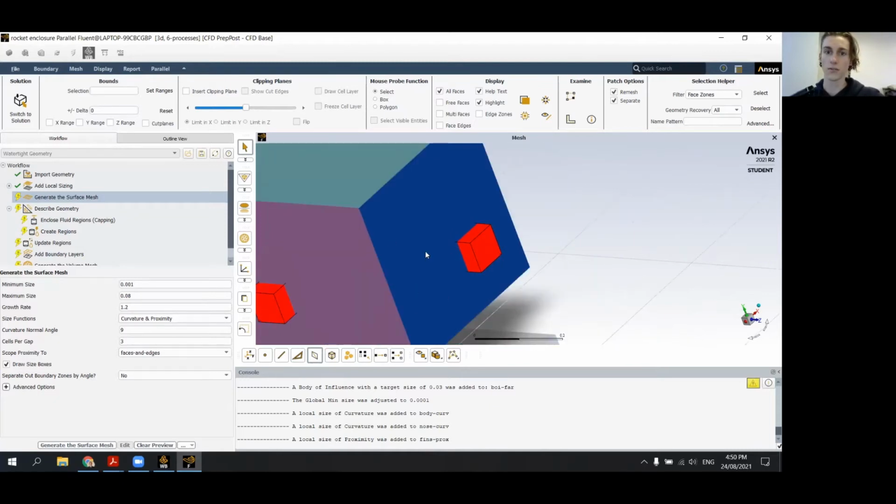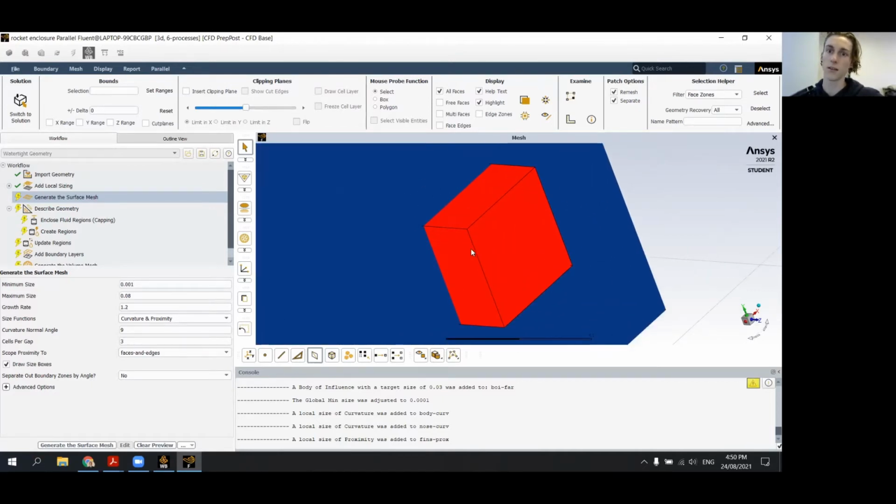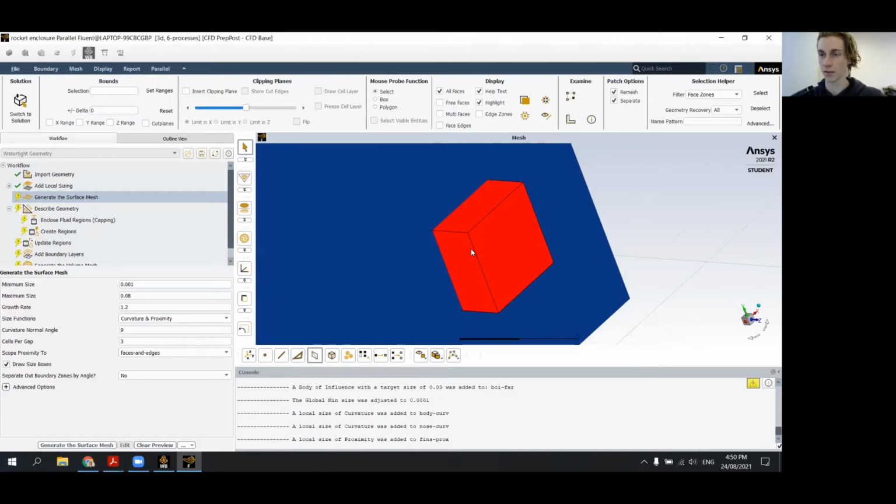If I think the pressure distribution is going to be really wavy and full of lots of tiny oscillations that I want to capture, then this mesh size needs to go down to capture those oscillations. And I need to reduce the size of the mesh to the point that I could draw straight lines and it would closely match the actual curve. Hopefully that makes sense to people.